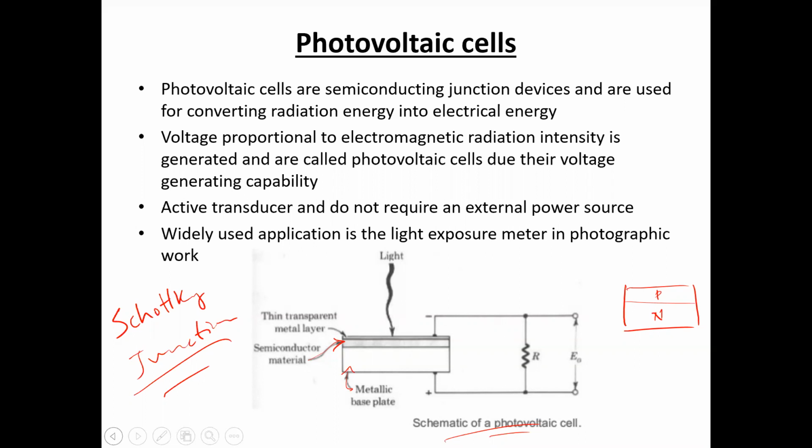if the cost of fabrication is an issue, because the Schottky junction solar cells can be fabricated at a lower cost, and the barrier potential that is present in the depletion region is also high in the case of Schottky junction. So considering the higher barrier potential and the lower value of cost in production, they can sometimes be used as the alternative of the p-n junction photovoltaic cells.